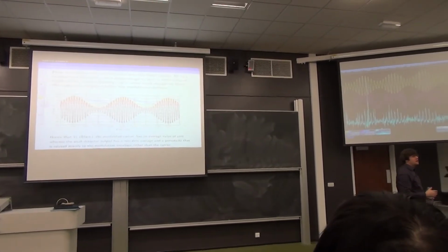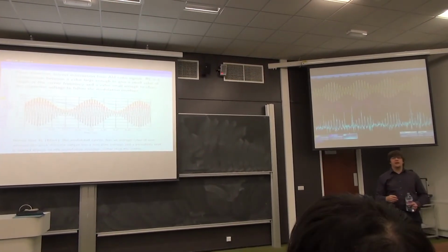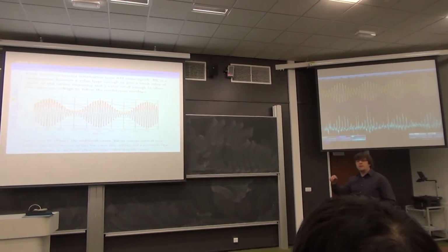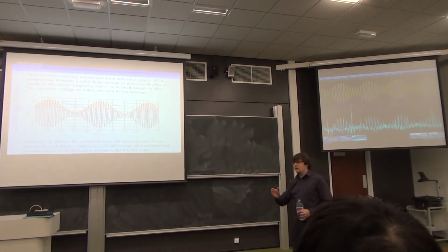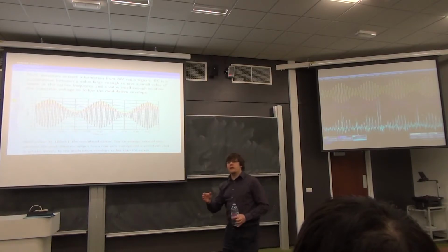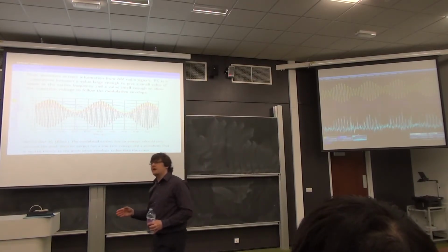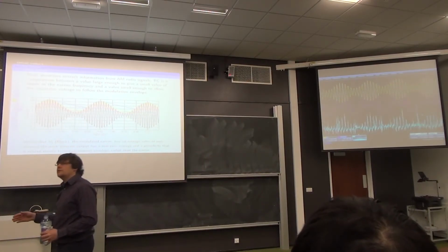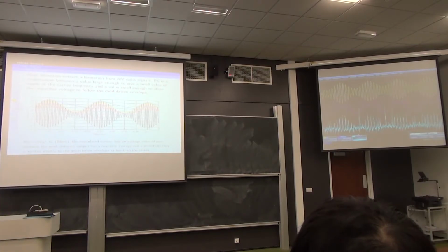And if the peak detector can't keep up with the rate at which that is falling, or if you look at the peak value of one carrier cycle and the peak value of the next carrier cycle, it is dropping over cycles. If your peak detector can't keep up with that rate of drop, you will lose information because your peak detector is not faithfully following the input waveform.